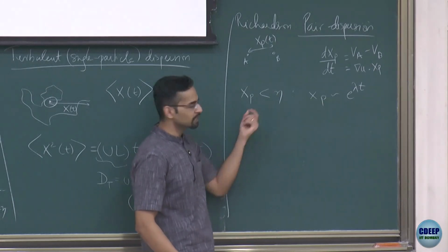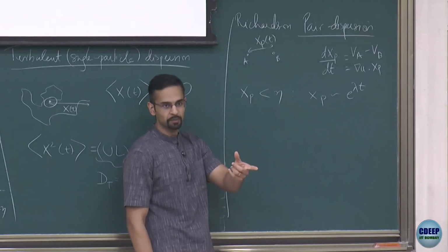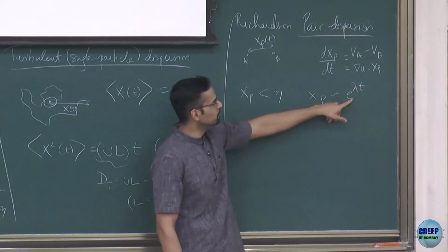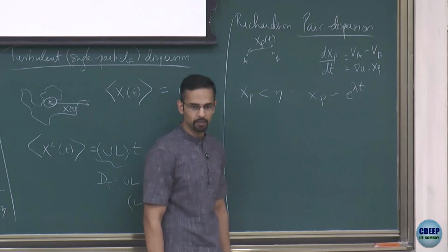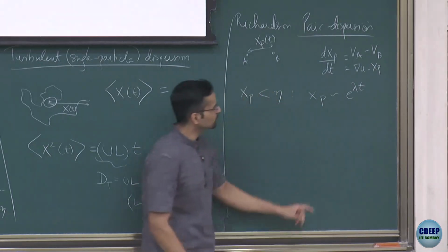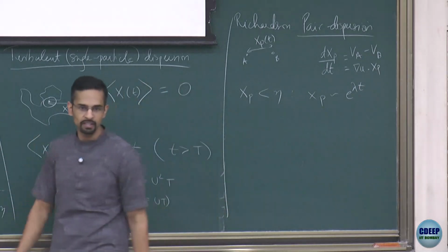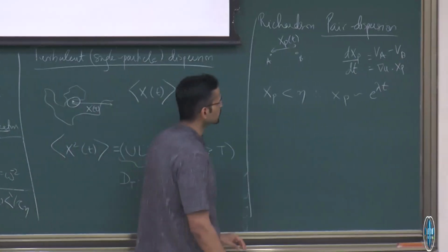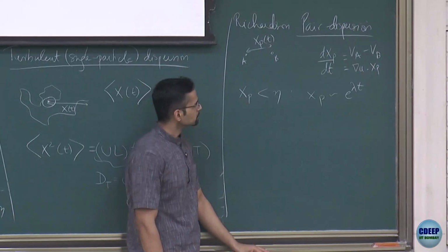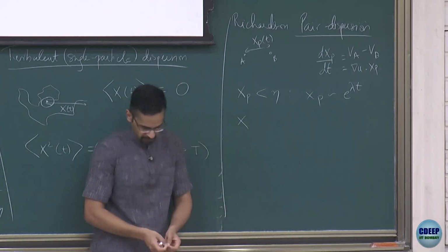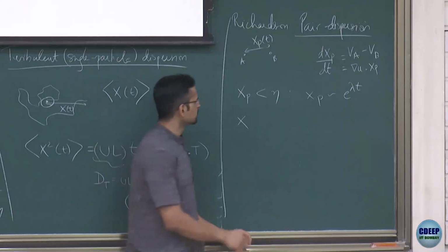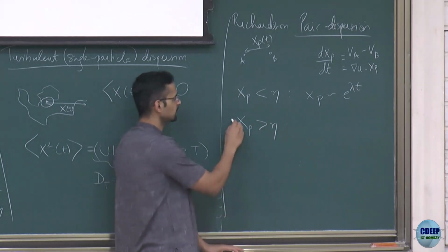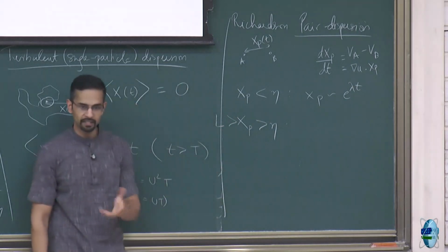So you imagine taking your initial separation so small that it takes infinite time to separate. Then you can wait for a long time and see how this behaves. Grad U will keep fluctuating, but it will give you a mean exponential behavior, and that lambda is a Lyapunov exponent. But leaving aside those details, the main point is at small distances you will separate out exponentially, the way you would in some kind of extensional flow. Then you will have this exponential separation, then you will hit distances greater than the Kolmogorov, but less than the large eddy. So now I'm in the inertial range.